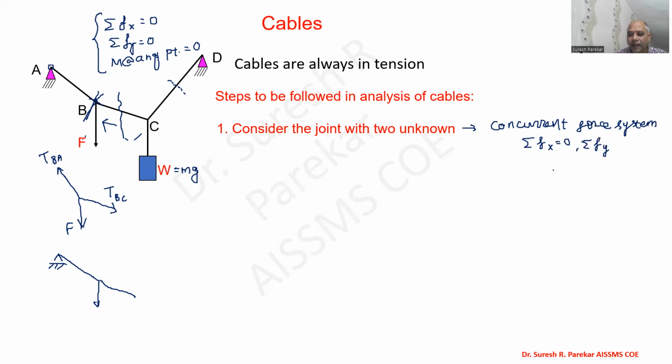We cannot apply the moment equation, because concurrent force system means forces are acting at a joint, and all forces are passing through the same joint.